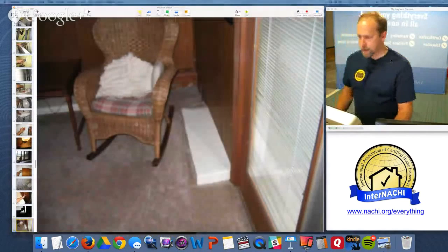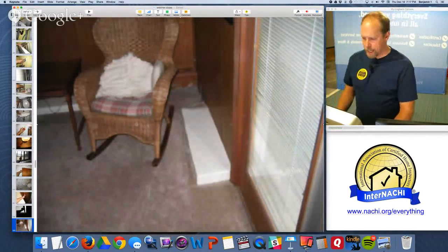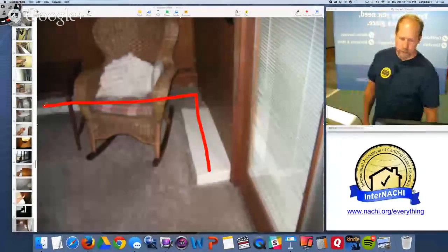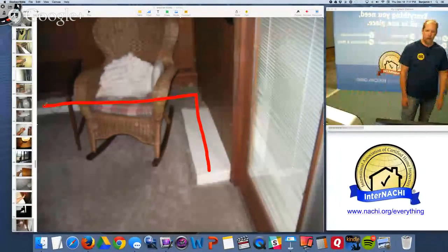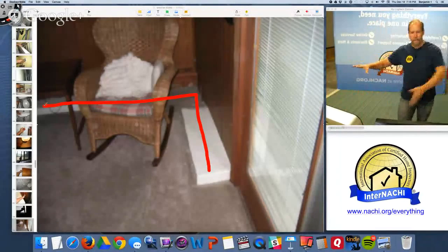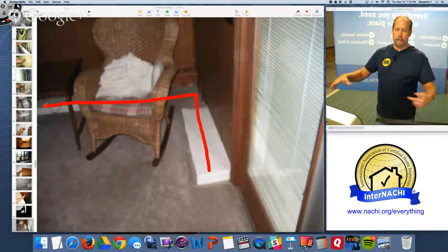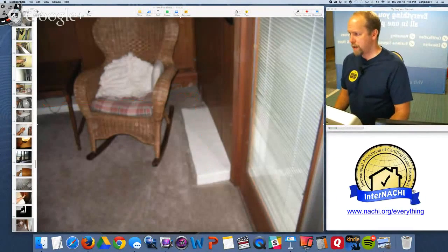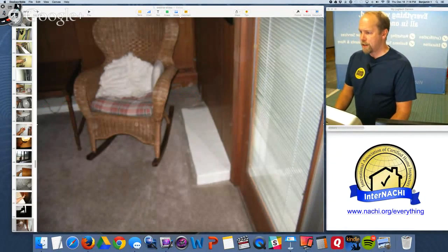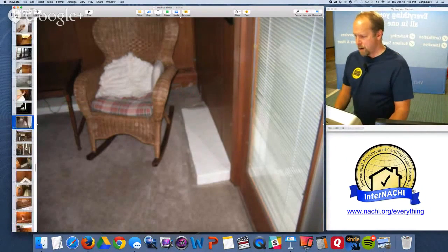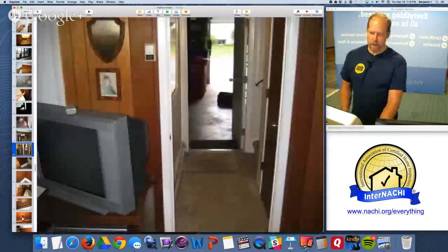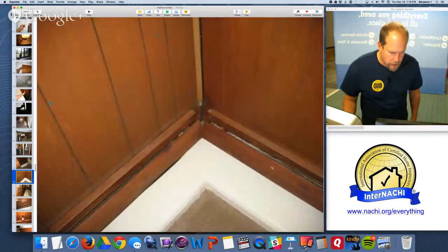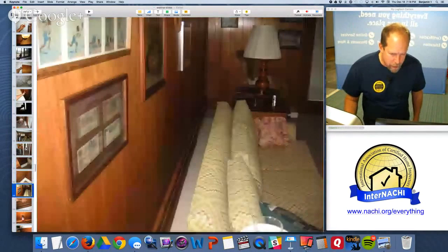See this in the basement. We're still in the basement here. And if you take a look, this is a perimeter French drainage system of some kind. That's a concrete block cover over a ditch, I'm assuming, with maybe some gravel and some pipe that leads all the way to the crawl space sump pump. That was an interesting way of doing that. So my hunch that there are water problems with this house is pretty much confirmed because they installed that drainage system. But they have furniture and it's a finished basement. You know, it's living. Looks kind of white paint. Maybe they recently painted it.